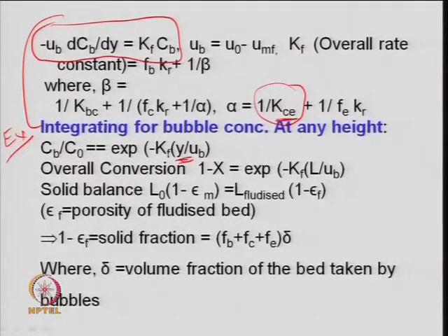Same thing is Cb, also for a given size of particles, the mean conversion or mean concentration in the bubble phase. So, one can find out this value or conversion value, and one can correlate that with the height of the fluidized bed reactor, y. And this is how we proceed for the design.